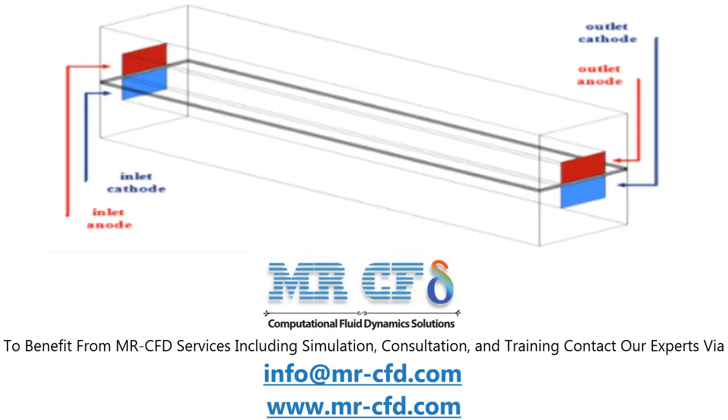The three-dimensional geometry of the present model is designed by Design Modeler software. The present model has a symmetrical structure and consists of 9 regions: 7 specific fluid zones, including cathode and anode flow channel, cathode and anode gaseous region, cathode and anode catalytic domain, and polymeric membrane, as well as 2 solid zones. The solid zones consist of a cathodic and anodic current collector.